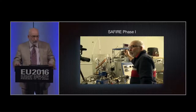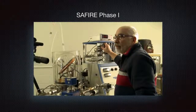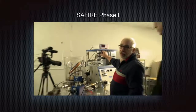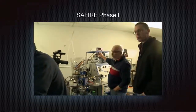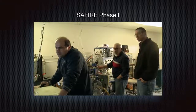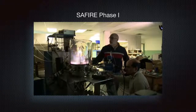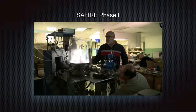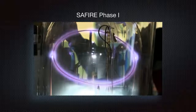We adjust pressure, voltage, current, and time. Time is also a key element. When the proper combination of these factors is arrived at, the plasma spontaneously ignites. I'm going to introduce a little more helium right now, a little bit more, and then we'll take another sample. There we go. Point 4 is going down. Let's shut it off. Pumps and argon are off. A glow discharge forms in the chamber.